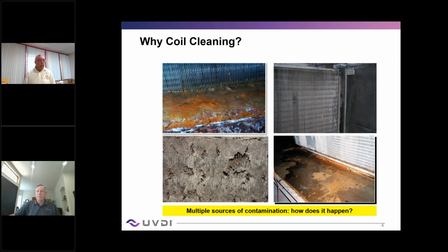Of course, mold spores are found in nearly every environment and brought into the building through door openings and outdoor air supplies. So even if you have a high efficiency filter, a filter replacement can cause a momentary breach and allow not just spores, but also organic matter and dust and particles to bypass the filter and get deposited on the coil.